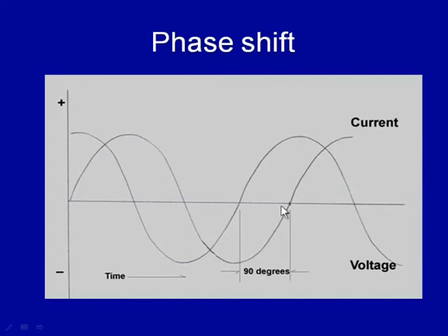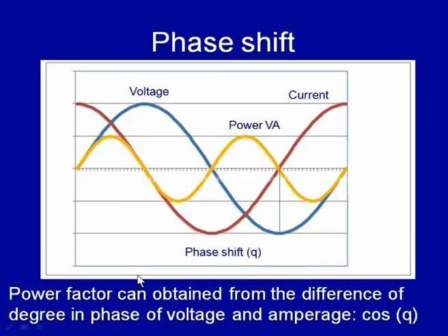So, efforts are made to have a phase shift such that when the current is 0, the voltage is maximum. This kind of shift is applied by using proper power factor for welding using AC, so that the arc can be maintained. We can see this more clearly here.